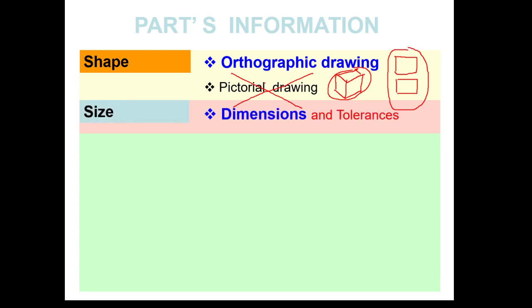Okay, size, yes, we use dimension lines, dimensioning format, and if you watch one of the previous video records, you see, of course, while talking about the content of the title block, I briefly made an introduction, saying that even in today's technology, it is impossible to set the size of a feature exactly equal to a certain specific number. For the size of each feature, there should be an allowance. We should use upper and lower limits, okay?